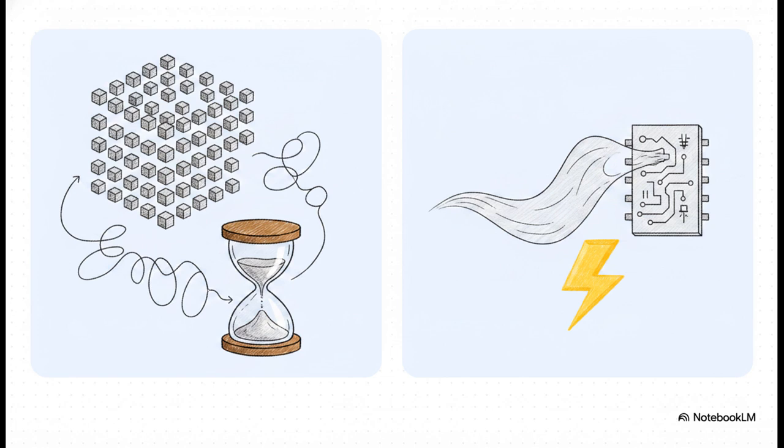software like HFSS or CST. You know the drill. Traditional tools rely heavily on FDTD, or finite difference time domain methods. What do they do? They artificially chop up continuous space into these tiny, discrete grids, right? And then they force a computer to grind through literally millions of iterative numerical steps. It's an absolute computational bottleneck, taking anywhere from minutes to hours and burning a ton of energy in the process.